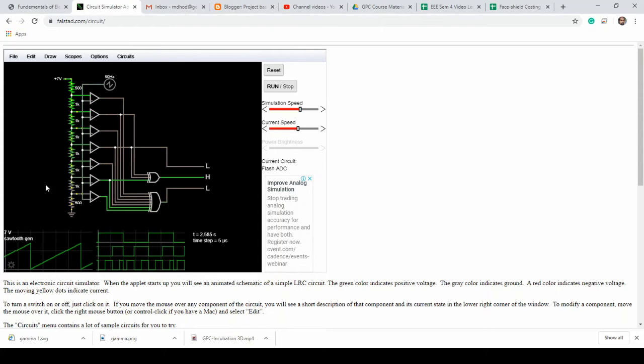Let's look at a circuit. Now I have a voltage ramp. It's a sawtooth wave, they call it. It starts from 0, goes to maximum, and then drops to 0, again goes to maximum and drops to 0. This is a sawtooth input coming at 50 Hertz. Plus you also have another reference voltage which is divided. This method uses voltage dividers to have the voltage divided from 0 to 7 volt, and this voltage is divided across many operational amplifiers.